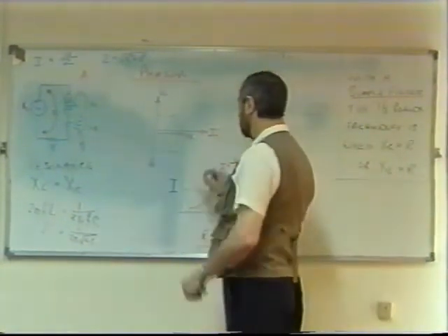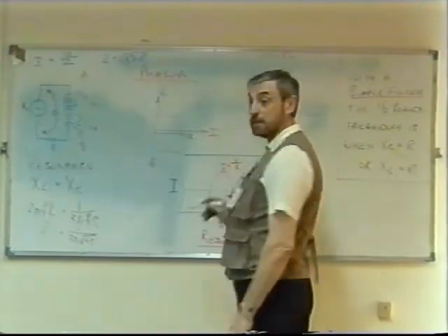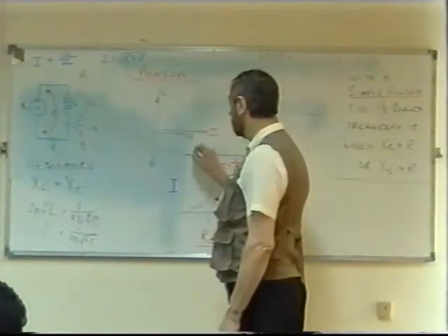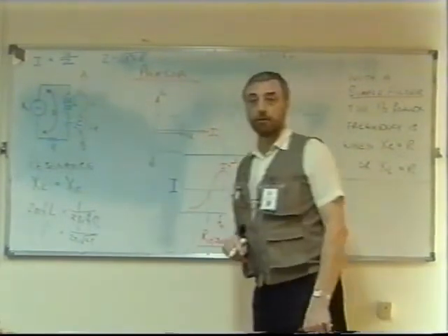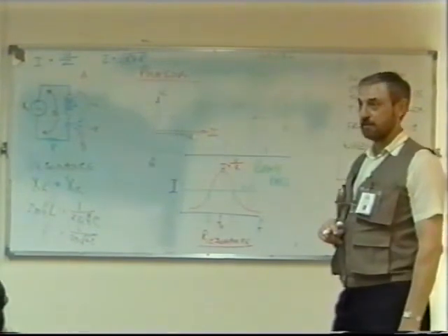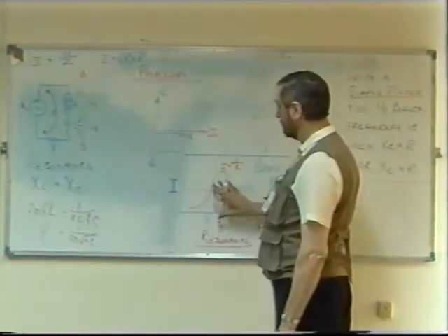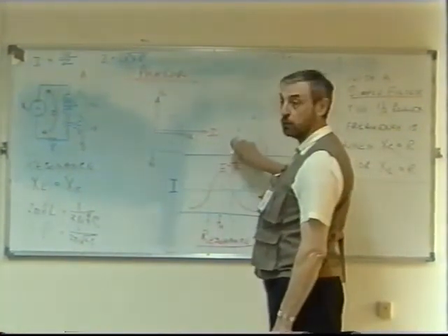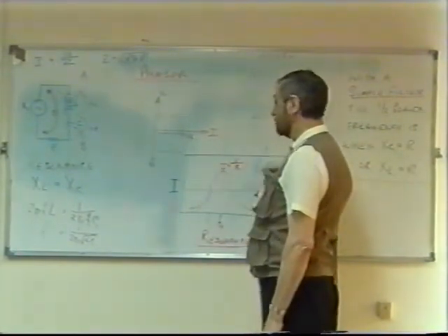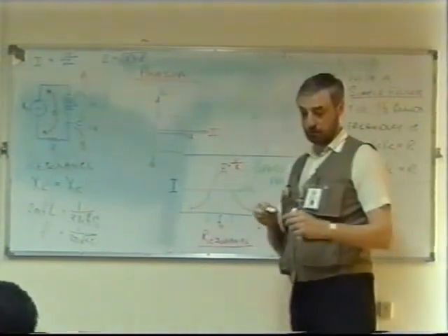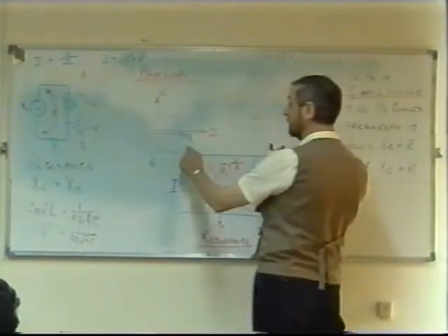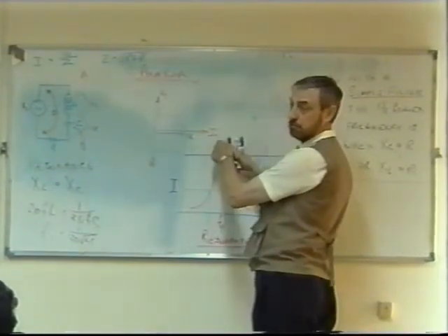If you had a receiver and you wanted to receive this frequency, but there are other frequencies above and below which could interfere, you put this bandpass filter over the frequency that you want. If it works correctly, these other two frequencies should be very much reduced, or rejected is the word we would use. These would be rejected, and that would be accepted.